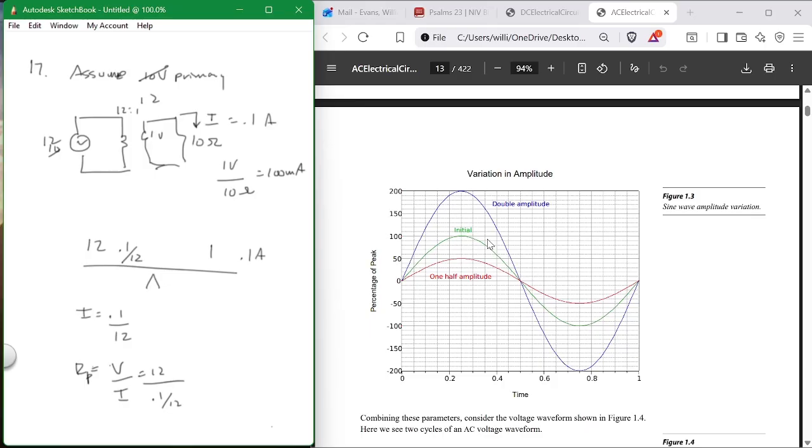Because when you go from single phase to 3 phase, you multiply everything times the square root of 3. What is 746? That's the conversion from watts to horsepower. Those are the only 3 numbers you need to remember.